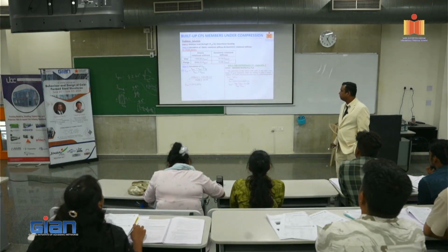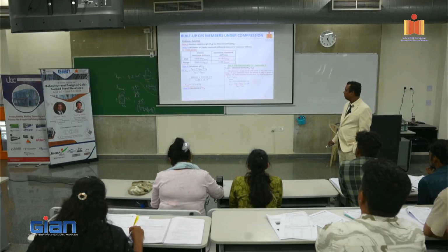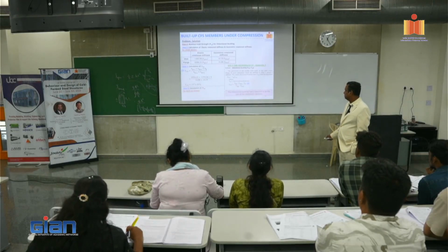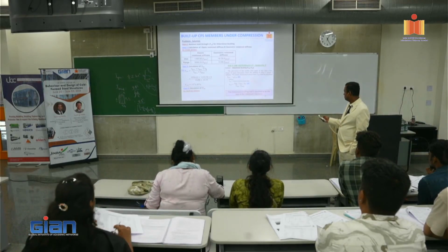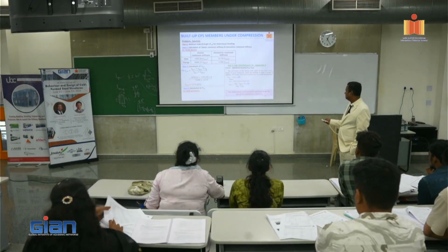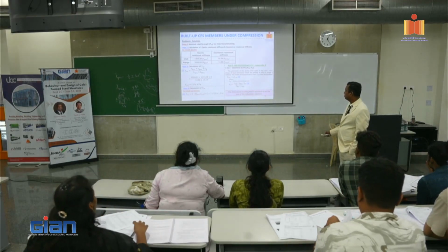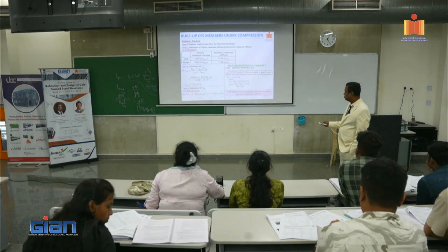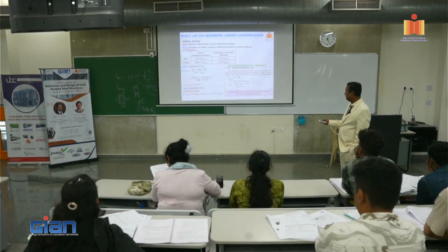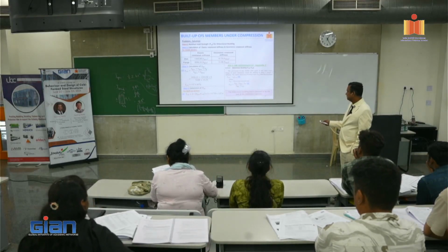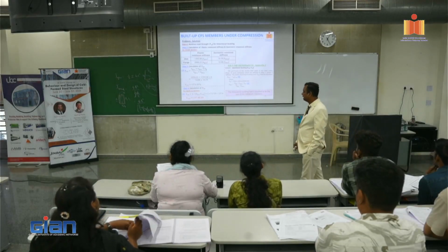So what do we do here? Now you have to find out PCRD, you multiply by A gross, right? So this A gross is given as this one. The distortional buckling load is assumed to be the sum of individual C sections. So you multiply by 2. Because this is for one section, 2 into AG into FCRD, which is 137.6, and you get a value of 197.48, which is PCRD.